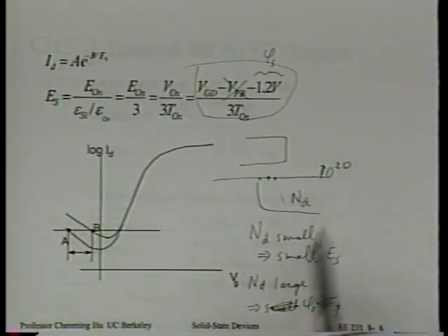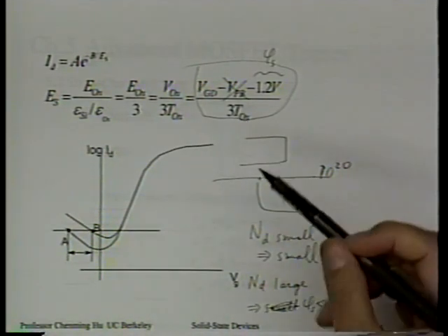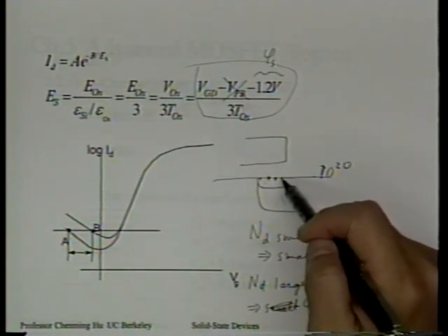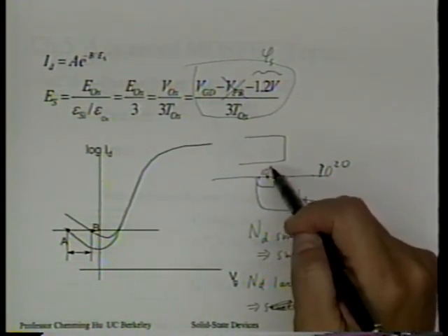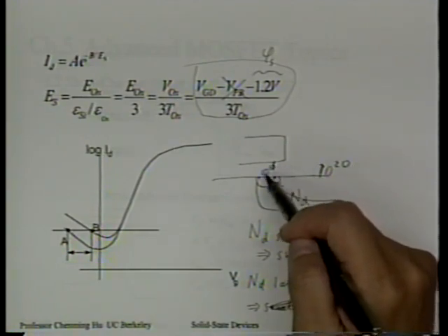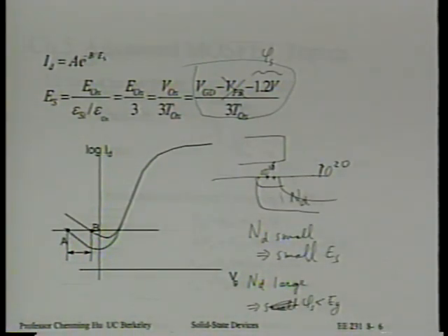What if the drain does not overlap the gate? Suppose, for example, we have LDD. If the doping concentration of the LDD is only 10 to the 17th or 10 to the 16th, we believe we can significantly improve the GIDL situation, because we're in case 1 now. Very small ND. We'll have to bend a lot. We need more voltage. Right? But unfortunately, that's not a very practical range to work with. That will hurt our ID set too much if we dope the LDD so lightly. You follow what I'm saying?